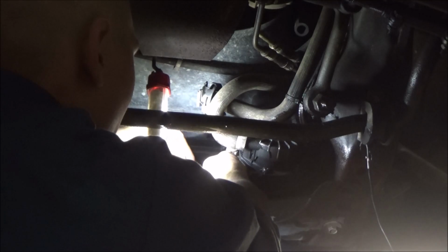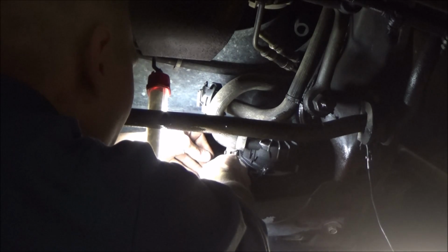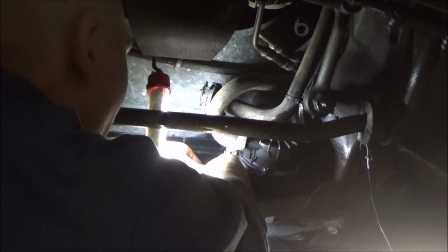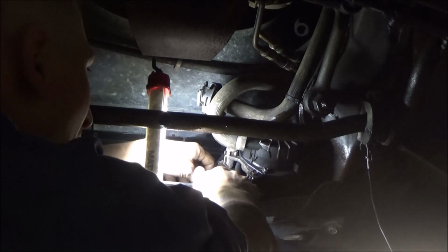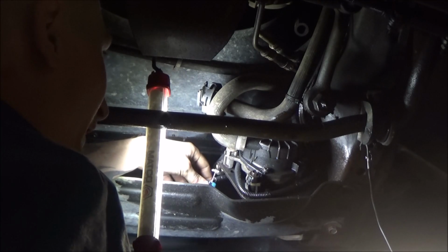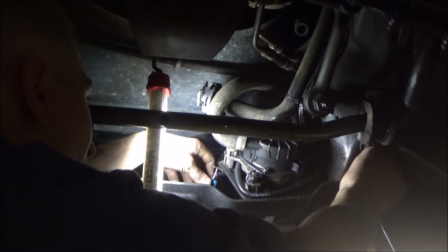So all I'm going to do, guys, is back probe the ground. And the reason I'm back probing the ground is just based on where this T-pin is. I don't want to risk shorting it up against the housing this air pump motor lives on. If I were to back probe that power feed, I could very easily blow the fuse in this location, and I'm really trying to avoid that.